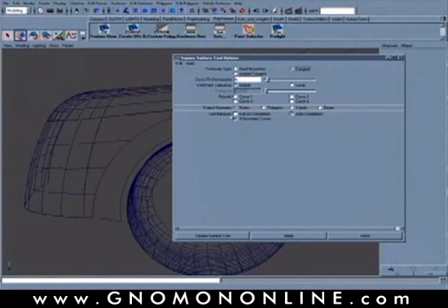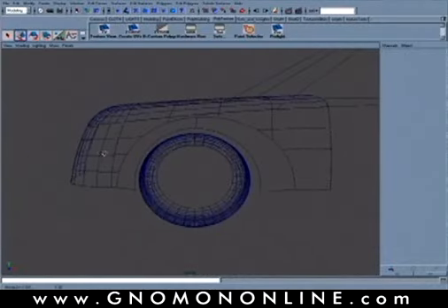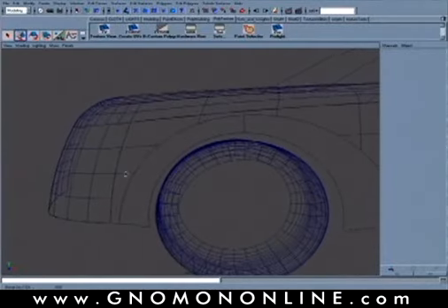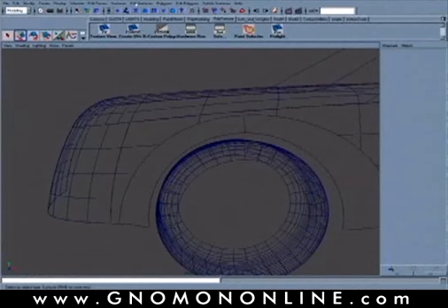Notice that if you use it as a tool, you get tool behaviors down at the bottom. One of them is we turn on to use 4 boundary curves, so that it will build 4 curves and then finish. If you turn that off, it would finish after doing 3 curves. Okay, so since we're setting this up as a 4 curve boundary, we want to make sure that that option is set up correctly. So go into the Square tool.